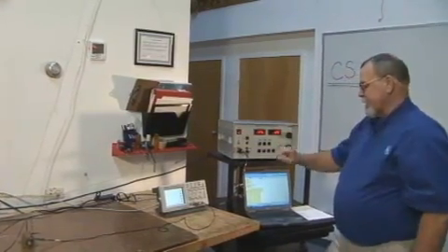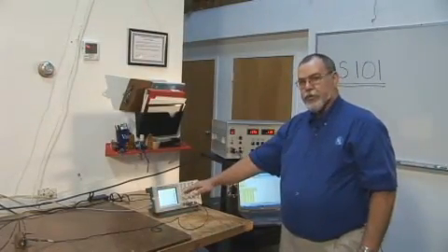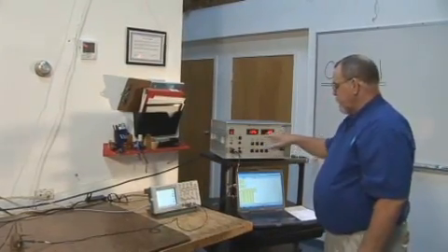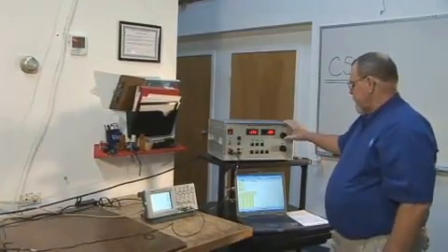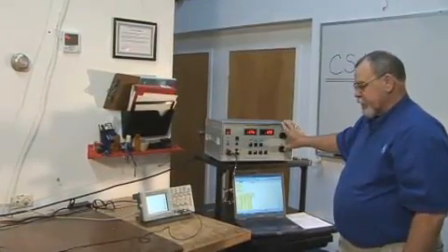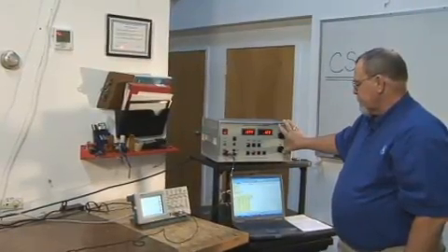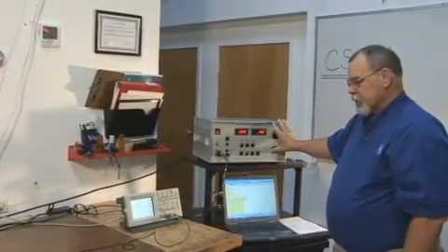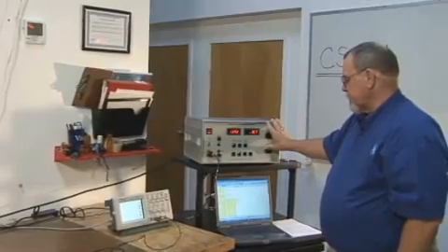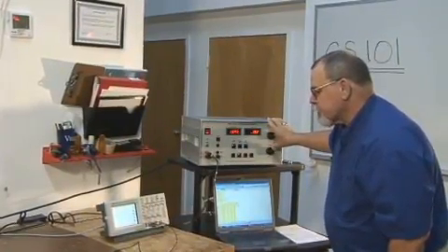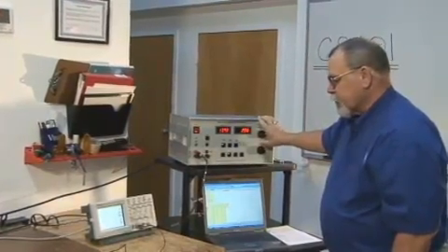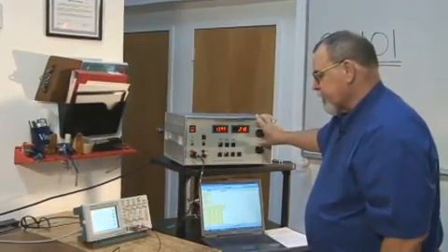As long as I can maintain my 6.32 volts while I keep my RMS voltage output steady, I'm good. So now I'm going to adjust the frequency, and I'm going to monitor the oscilloscope for the changing waveform to see that it stays sinusoidal. If I start seeing that it drops below 6.32 volts, I'm going to adjust the level to be higher.